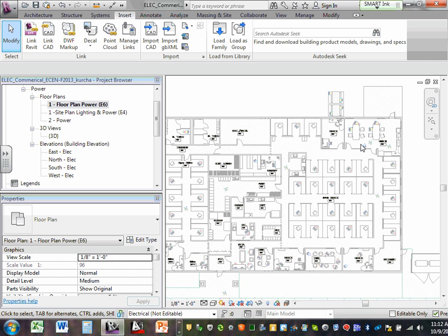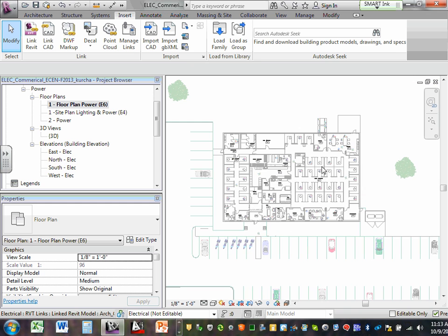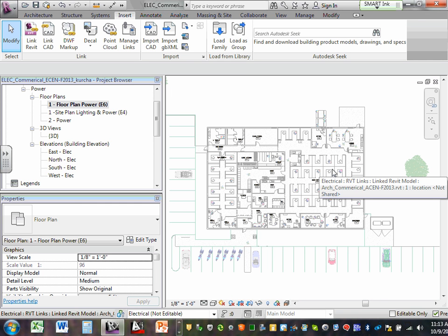You know what this monkeying around is? It's just instead of you going there and typing the names, which the architects would do anyway, they're already there, so we just brought them from a CAD file. But the process is very important, because that's how we're going to bring the lighting fixture layout into Revit. We're going to do the same process later on, bring from CAD. So what I wanted to emphasize here is this is the way you bring files from CAD into Revit.